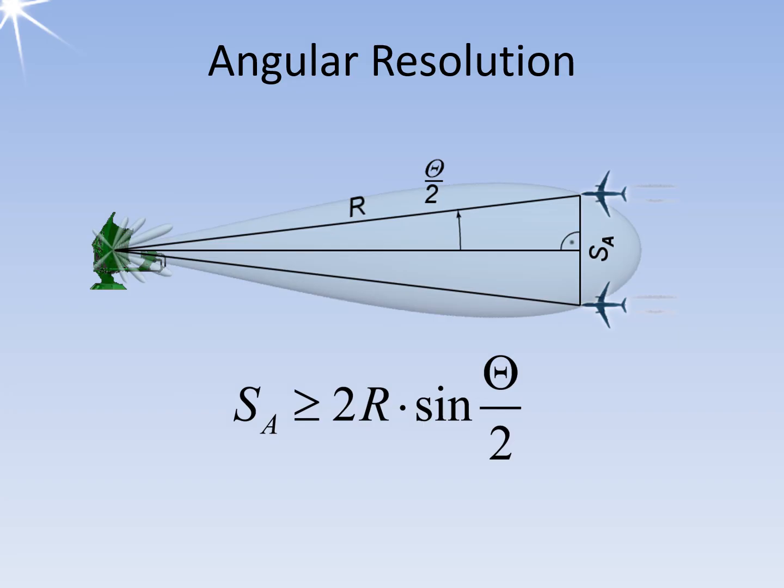However, very modern radar sets can still distinguish between one or two targets even if both are flying directly next to each other. Then known radar signatures are evaluated, that is, all changes of the echo signal compared to the transmitted signal, like a fingerprint. This can include, for example, changes in Doppler frequencies caused by so-called jet engine modulation. This is, Doppler frequencies caused by the rotation of the compressor blades in the turbines. The number of engines can thus be determined and plausibility with the other data can be established.